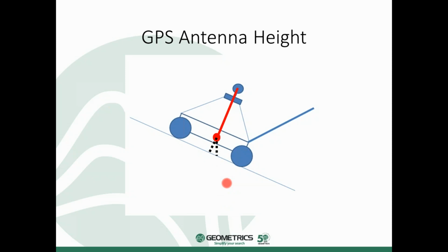So what you could do, and this is going to be up to the field crew and the project geophysicist, is if you really want this position here to be displayed on the navigation screen, you can just set your GPS antenna height to be the height from the ground.